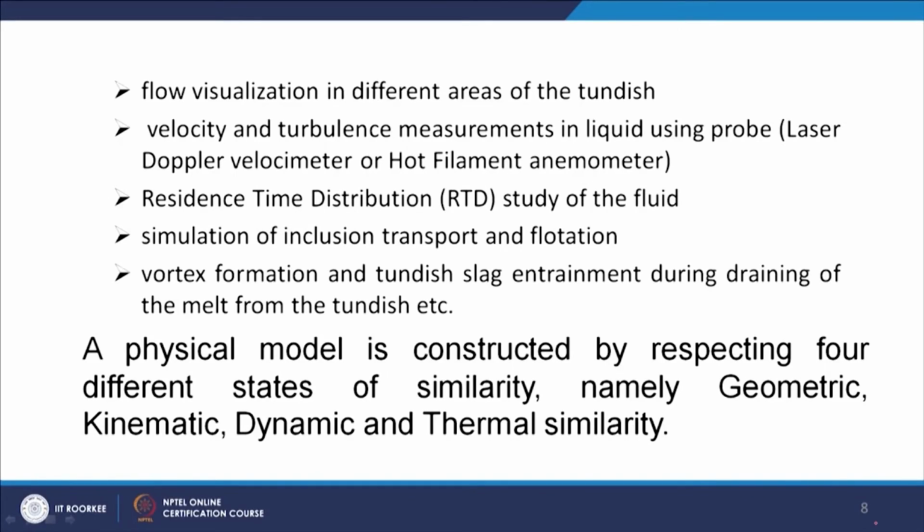Simulation of inclusion transport and flotation. That also can be done using physical models. You can make a model and have inclusions of different shapes and sizes, of different material, which can float inside the liquid. Accordingly, the density of that inclusion has to be taken into account, to see how they are transported to different regions of the tundish, and how they float up. These can also be predicted.